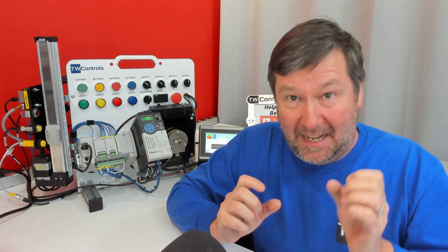One really cool feature of the Micro850 and Micro870 PLCs that have the E in them, such as an L50E or an L70E, is they support implicit messaging, which is similar to how we add devices to our I/O configuration in Studio 5000. Now, as cool as that is, if we can connect to them over Ethernet, we also need to know when we have a connection issue.